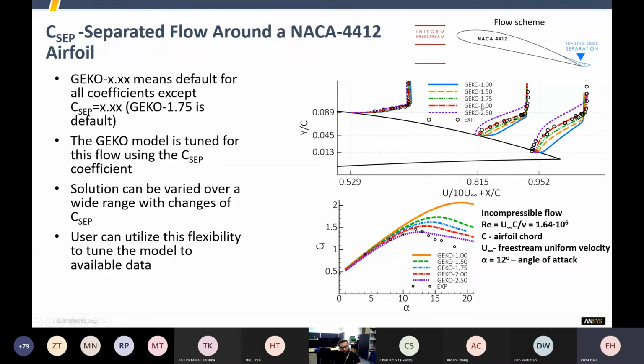And put them onto your other model, where you're not matching up against your wind tunnel. You're actually looking at the performance of the vehicle around a track. This can provide you with a much higher accuracy because you can calibrate the model for the wind tunnel application. So you know that you're getting good values for your mesh density and your vehicle geometry, and then take that to the rest of your models, which you can't necessarily validate, but you now have a better idea that it's going to be accurate based on the calibration that you've done.